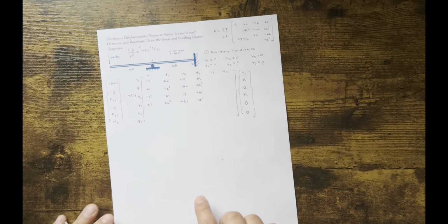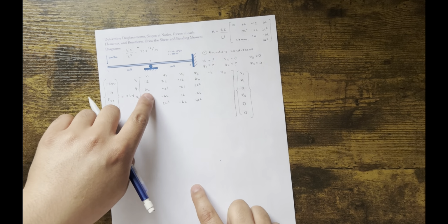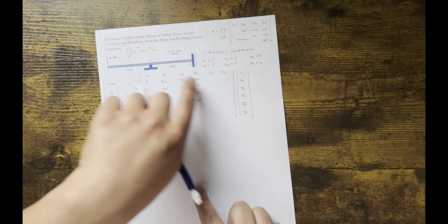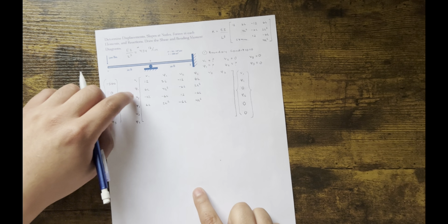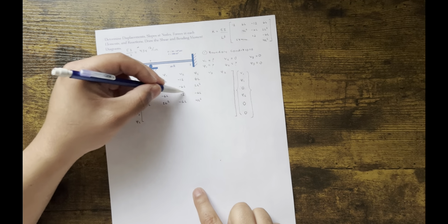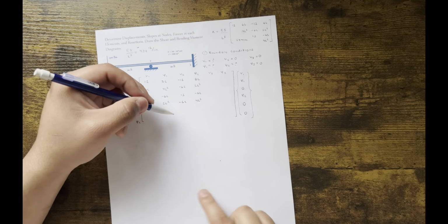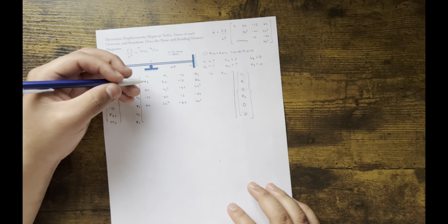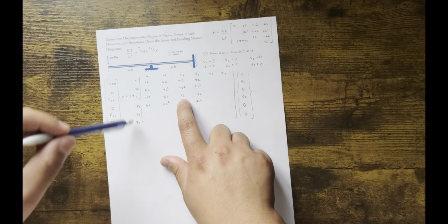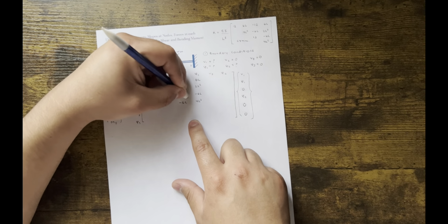That's all that happened. Now that's for beam 1, okay? This is your matrix for beam 1, your stiffness matrix. And then beam 2 goes here, V2 all the way to Phi3. So from here, all this, okay? That is beam 2, or element number 2. So in this case, if you add it, right, that becomes double. 12 plus 12, right? So you're gonna have 24.